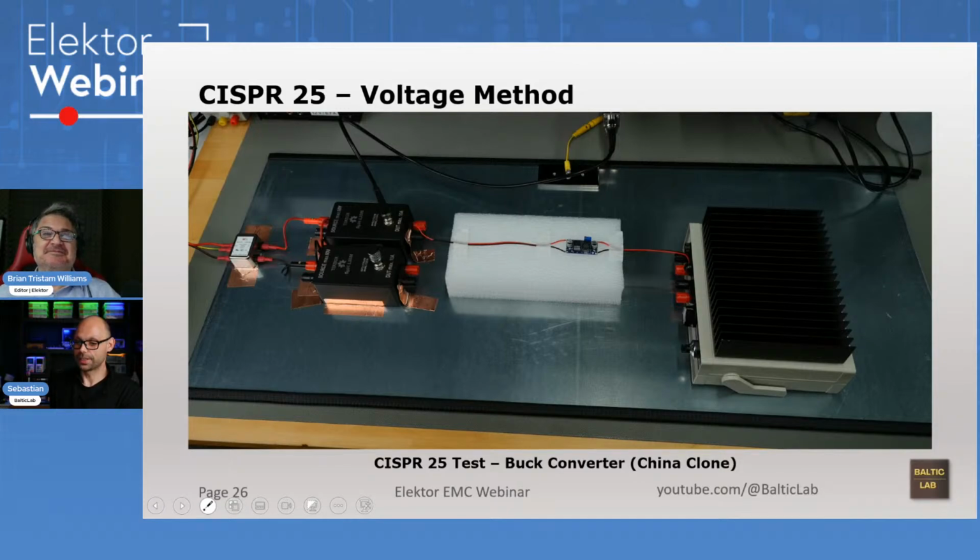I guess the things that surprise me are air gaps that work. Like when a connector is broken off its PCB trace, but the space is apparently close enough that, say, a low noise amplifier at 10 gigahertz or above just lost 20 dB of gain, and you can't figure out why.